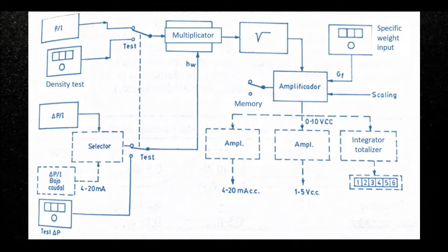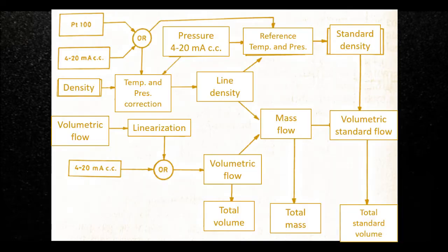It has an accuracy of plus-minus 0.2% of the scale. A calculating unit that compensates gas flow for gas density variations with manual specific gravity corrections. Its characteristics are similar to the previous unit. It has an accuracy of plus-minus 0.15% of the scale. Digital compensation with microprocessor. The calculation of the module factors is done automatically when entering the measurement fields of the flow, pressure, and temperature transmitters. If these are intelligent instruments, the measurement field can be changed if required. And a higher final accuracy is also achieved by having linearization and viscosity compensation.